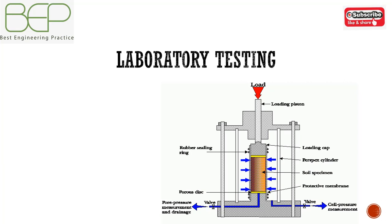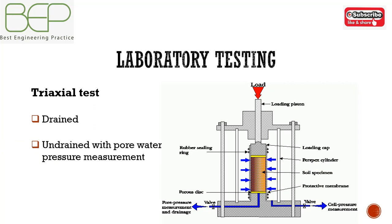Tests can be carried out either drained, where a drainage vent is left open to a fixed water pressure during shear, which must be carried out slowly enough to allow excess pore pressure set up by deviatoric stress increase to drain. Or undrained with pore water pressure measurement, where specimen drainage is prevented and the pore pressure in the specimen is measured during shear using a pore pressure transducer.